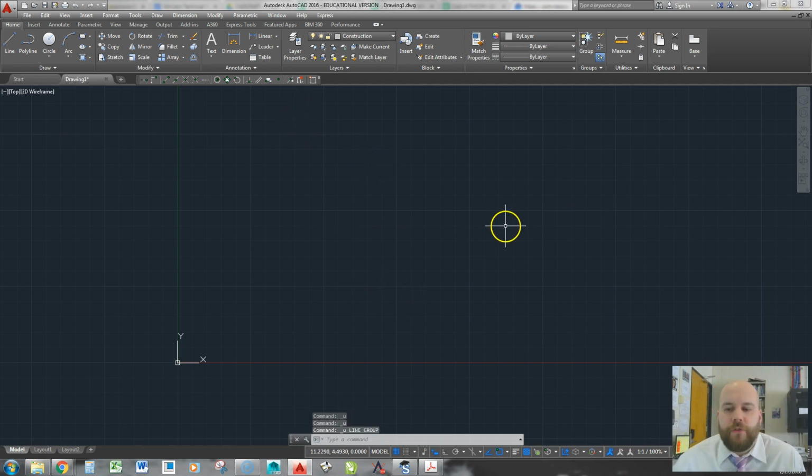And when you're creating construction lines, for those of you that haven't drawn on a board, this is how I originally learned how to make drawings, by drafting in theory on the board. So I like to reference that as much as possible for my students. But construction lines are these big long lines that you're going to draw very lightly, and then you'll draw darker lines where your object lines are located.